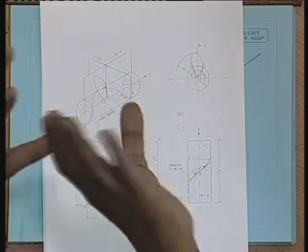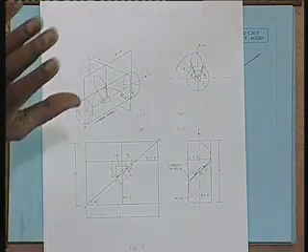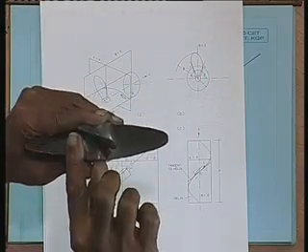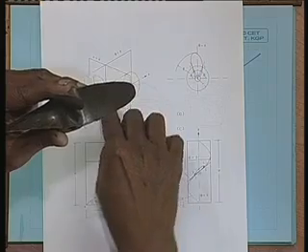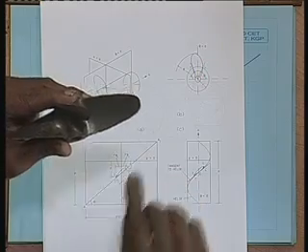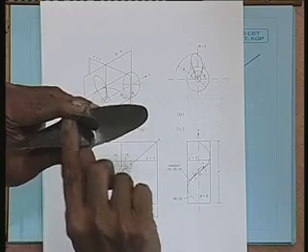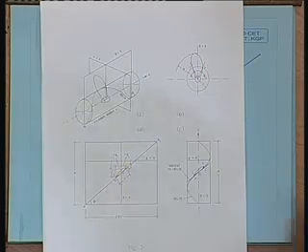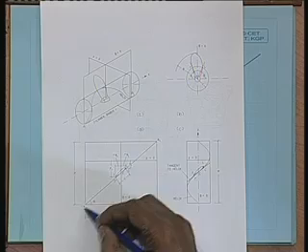Remember, what I have actually done is taken the propeller at a constant radius. A constant radius is not a flat line. The section shape I have shown here is not a straight line; it is at a constant r. What I have shown is how this section would look if that radial arc was made into a straight line. Do you understand? We expanded this to a straight line, isn't it?